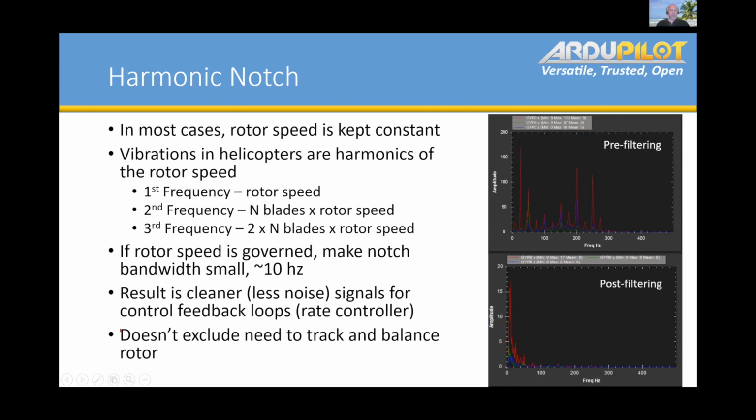Big point here is that the harmonic notch is great, but it does not exclude the need to track and balance your rotors. You really still need to go out and understand how to track and balance your rotors and do it well. It certainly helps, but you really want to make sure you have good track and balance.